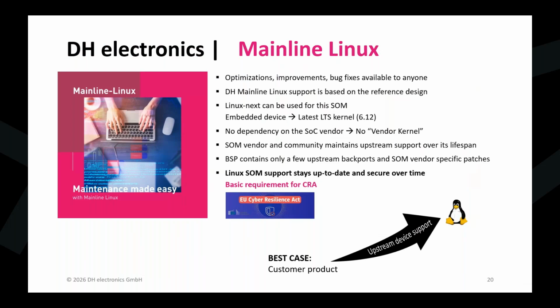But for embedded devices, the normal way is to use the latest long-term support kernel. And currently, this is the 6.18 kernel. And this is exactly what is part of our Yocto board support package layer. This will also make it easier to maintain the Linux support for your device, as not only DH, but also the whole Linux community will be providing the maintenance.